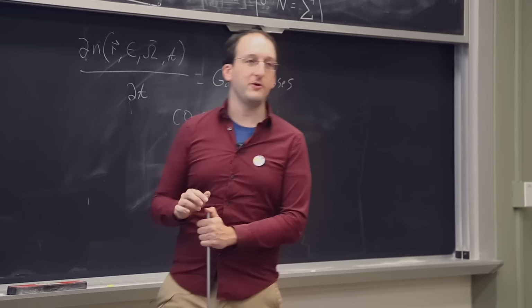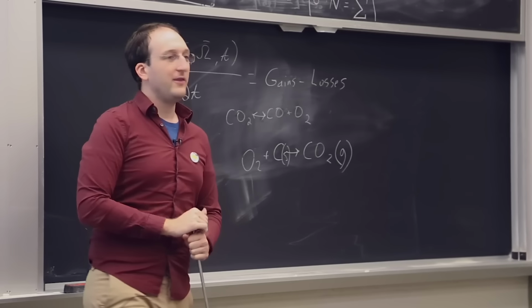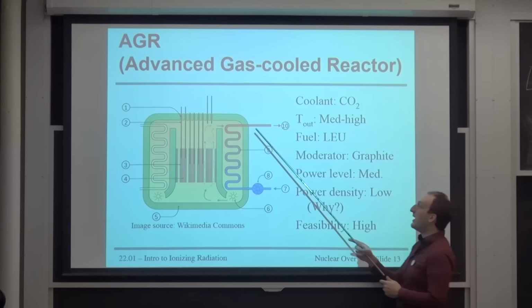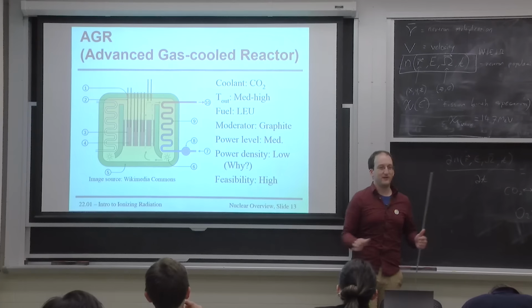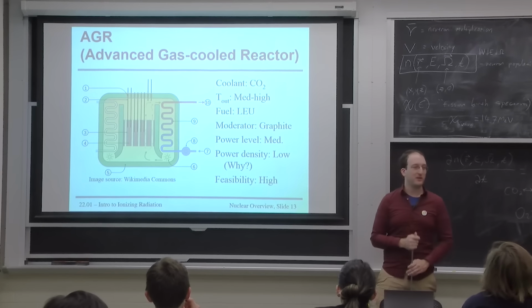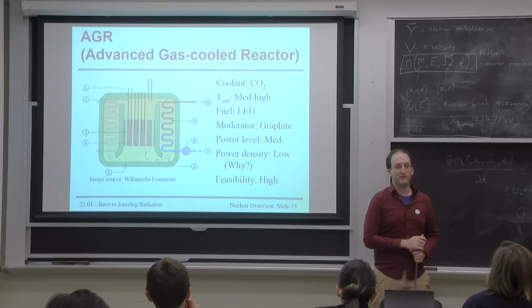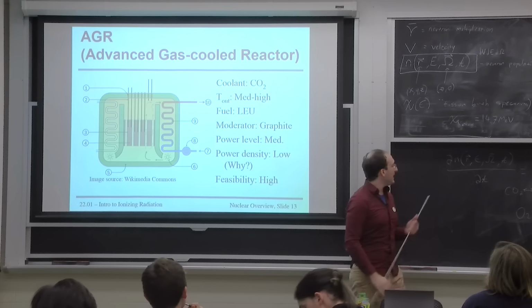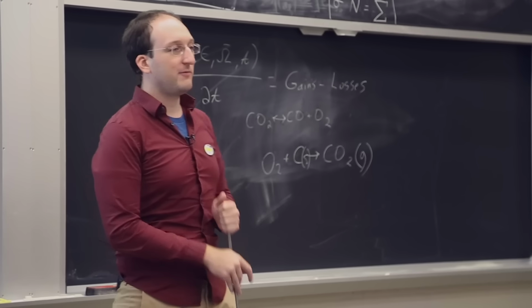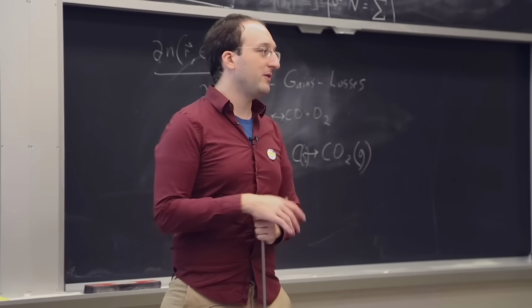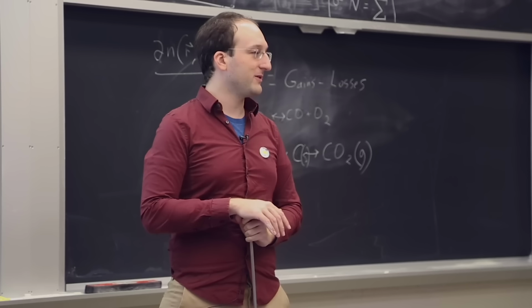In talking with a couple folks from the National Nuclear Laboratory, they said that 40 years later, when they took the caps off these reactors, a lot of that graphite was just gone, with a good explanation. It vaporized very, very slowly over 40 years or so, due to this natural recombination with whatever little bit of O2 was in equilibrium with CO2, and possibly some other leaks. I'm sure I wouldn't have been told that if there was a leak.